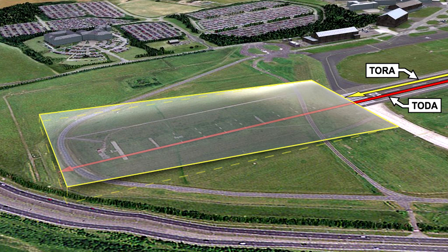You may recall that there was a maximum permissible length of clearway which equated to 50% of the TORA. This makes the maximum possible TODA 150% of the TORA. In simple terms, the TODA is the TORA plus the clearway, if such a clearway is present.